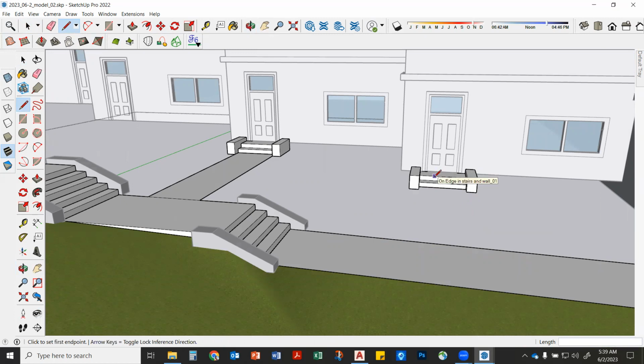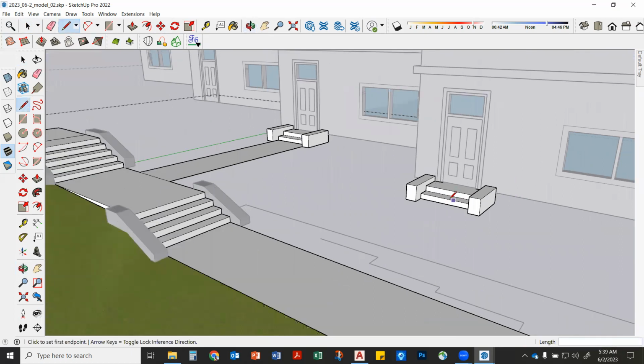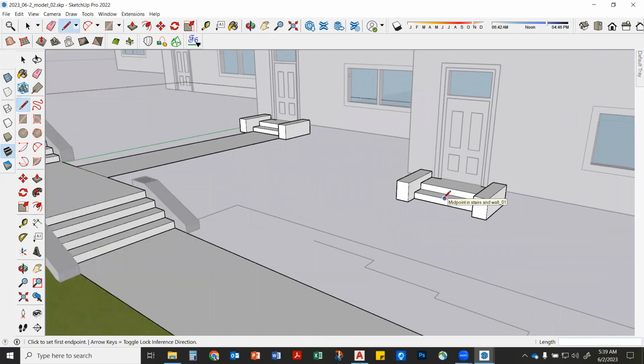So in this instance, because everything's orthogonal, everything's 90 degrees, it lines up with the axes. I can come in here and do that the same way we did it last time. It's similar to how we did it last time, but it'll be a little bit different. Watch. When we click here, we're going to lock it on the green axis.